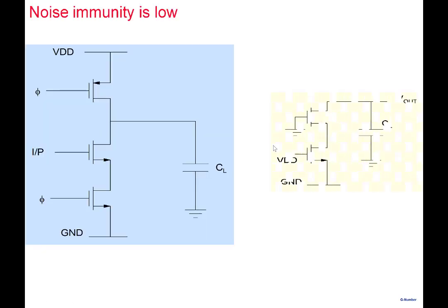But then this is what I was trying to point out to you here, look at that in evaluation phase. So upper part doesn't matter. This is ground. And lower part, this is VDD here. So this is enabled, clock is 1. So this is the situation. And I want this output node, which is floating, to remain at VDD. But then this transistor that you see here has a leakage current. So this capacitor here sort of leaks charge.